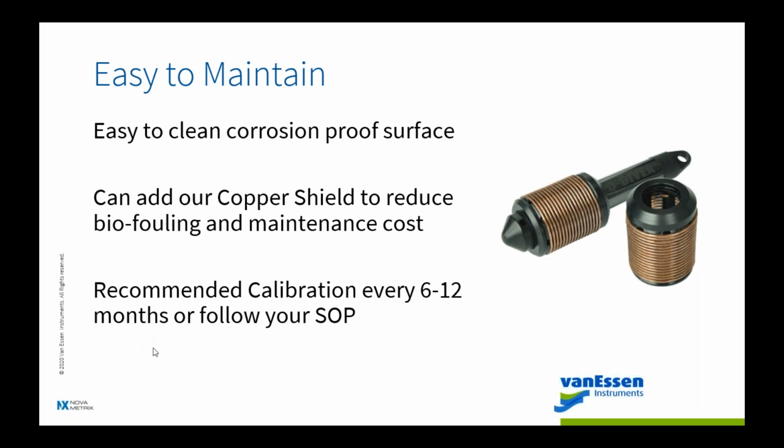Recommended calibration for these units, we typically say every 6 months, maximum 12 months if you can. Make it at least once a year, or at least follow your company's field instrumentation standard of practice.